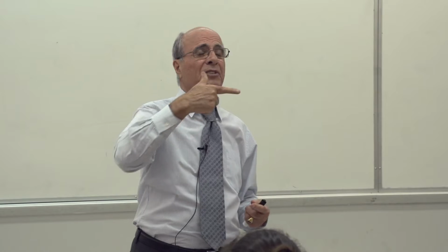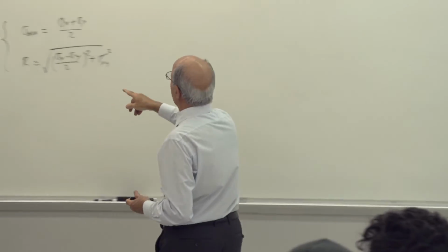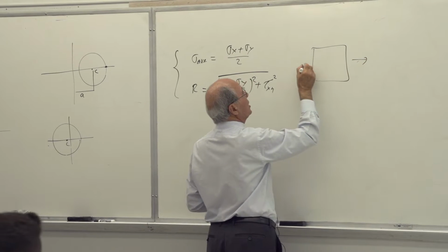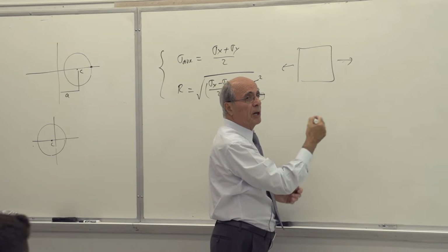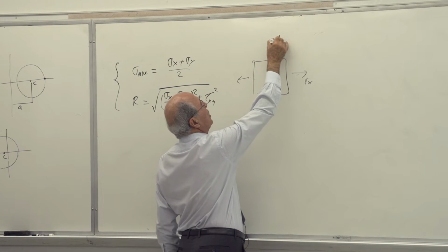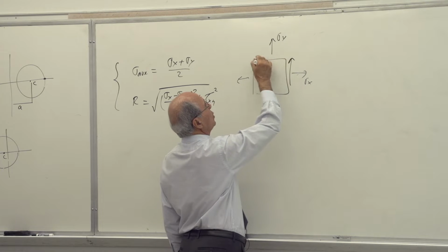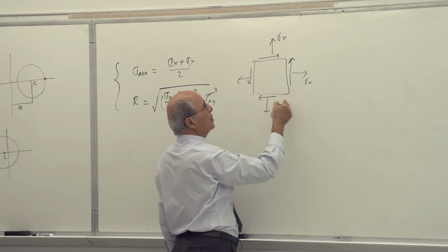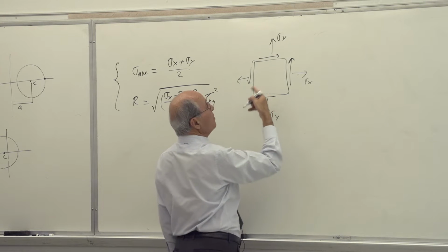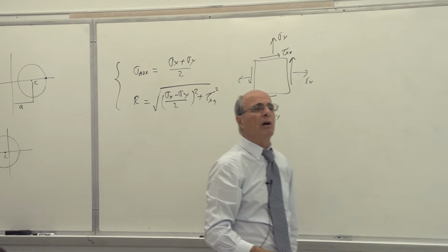That's the whole thing. You have calculated your stresses in the x and y direction. Where is this number coming from? As we said last time, it comes from here. Again, this is symbolic. I'm putting everything positive. This could be plus or minus. This could be plus or minus. And this also could be plus or minus. So in a plane stress scenario, we have a sigma x, a sigma y, and a tau yx, which is equal to tau xy. The two taus are equal, remember?